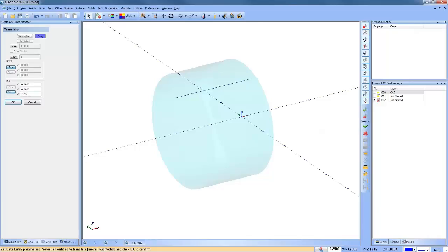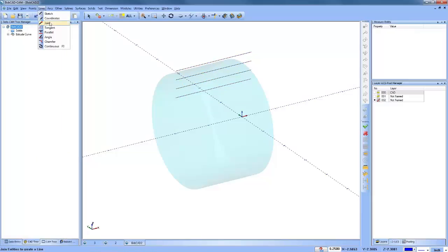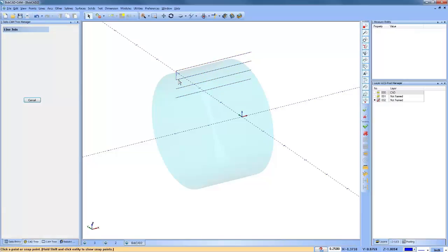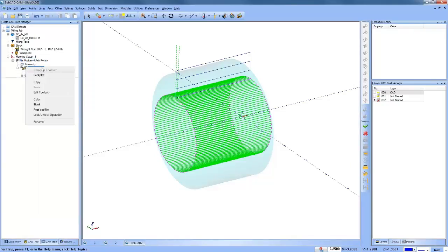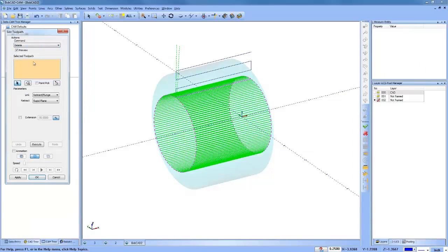We'll make it a little bit easier, so we'll make it 1/4 inch, and we'll say make 2 copies or 3 copies. All right, we'll say OK. Then we'll join this up. We'll say line join from here to here, here to here, here to there. So that becomes that. Then we can come back in and edit this. We're going to do a replace.